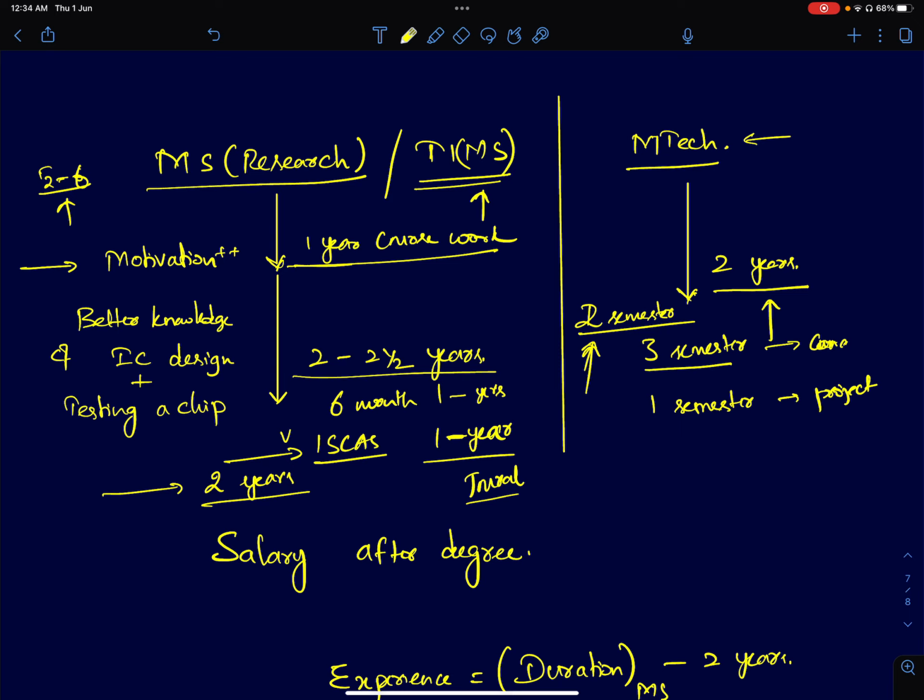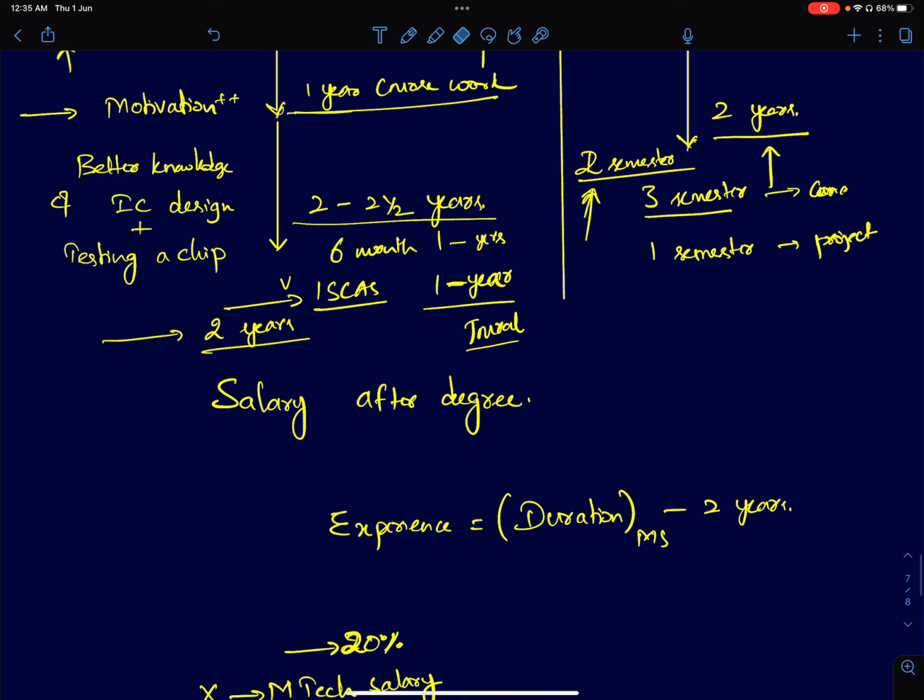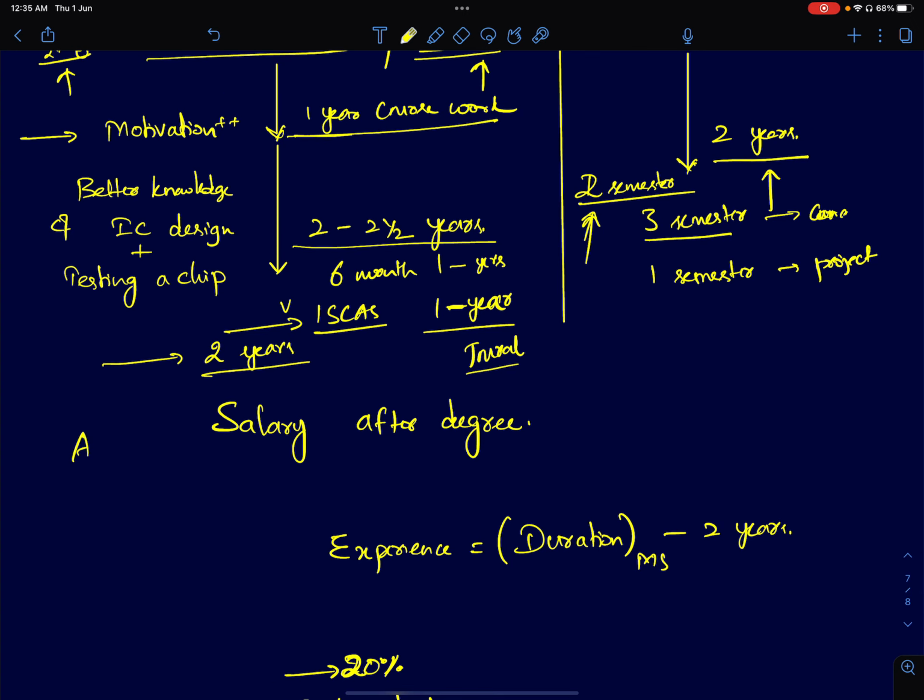The benefit you get as an MS by research student is a complete IC design cycle, from architecture. I said very briefly, I'll probably make another video talking about IC design cycles. But very briefly, you start with architecture, and once you're done with architecture, you go through the design phase. Design includes mostly schematic design. When I'm talking about architecture, normally you evaluate the performance of an architecture at the system level, using either MATLAB, Simulink, or Python. I use a combination of MATLAB and Verilog on Cadence. I'm comfortable with both.